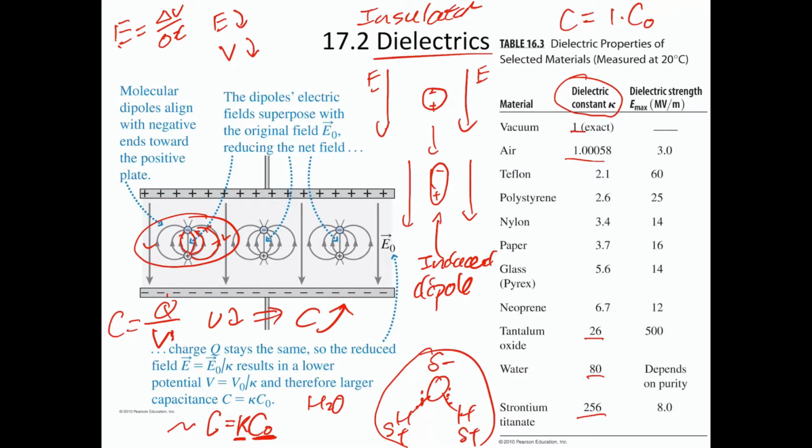Now all these numbers are important because when we try to squeeze our circuit into small integrated circuit IC chips, the capacitor is one of the components that needs to be squeezed into a small nano size. But if the area becomes so small, you have to make the gap small, but at the same time, you also want to find the insert material which produces high capacitance. Another column here, can you see what this means? It is the maximum voltage, maximum electric field, of course meaning voltage.